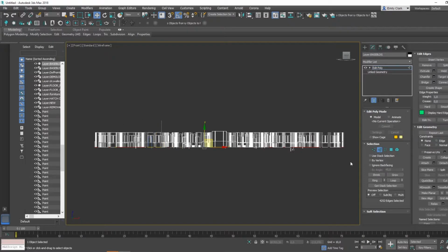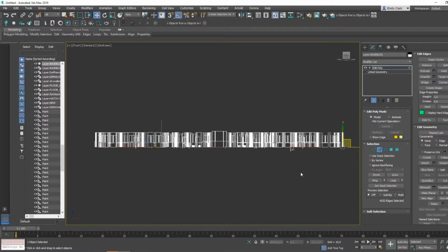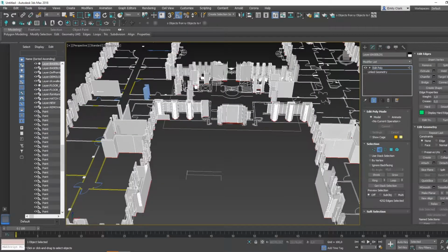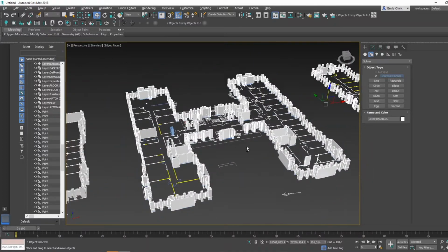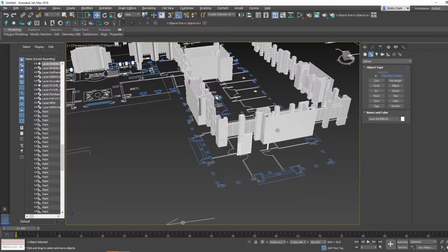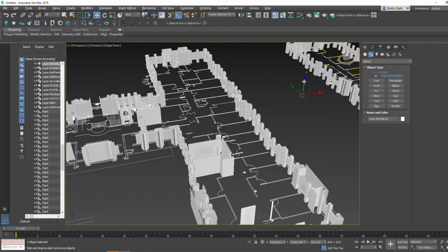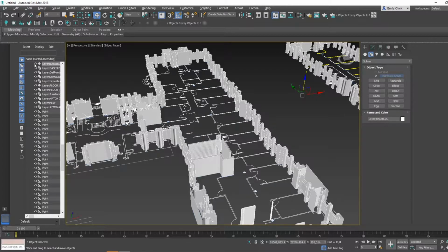So by doing that, I just highlighted this bottom area and then hold Alt and click that, and then I'll say create shape, linear, so okay. And now if you lift this, you can see that we've just got our splines for the base build, which is great. So we can actually just hide this.